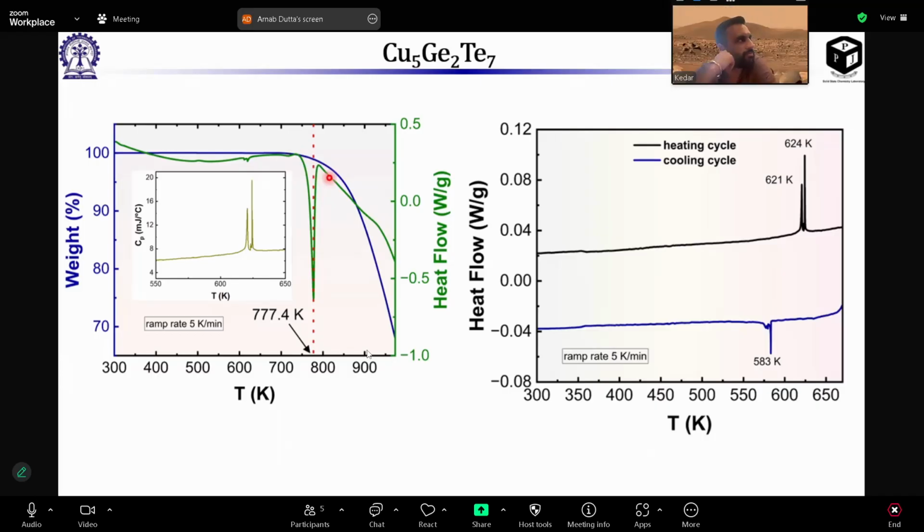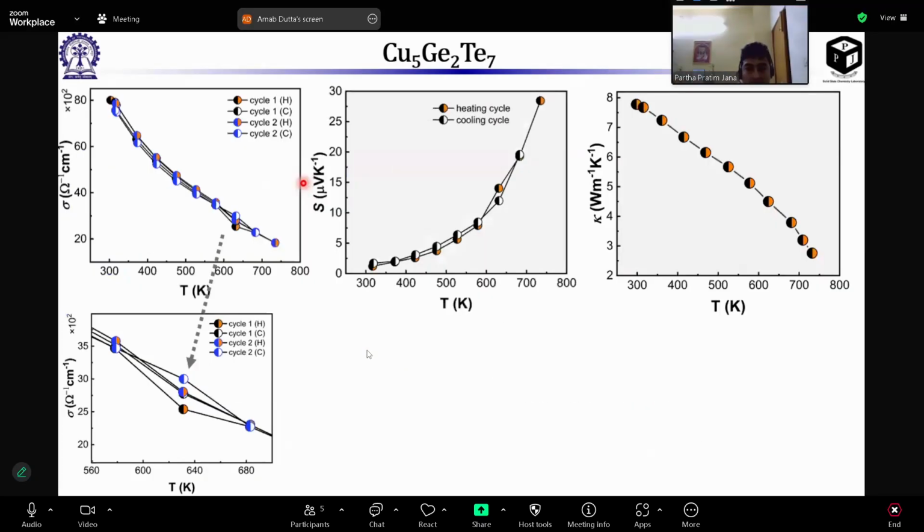That's cool. It might be good to do TEM on those for the paper. You take a sample as made, and then one that has gone through the DSC cycle, with the precipitates forming, if the majority phase is still that. We should also measure the transport properties of those, because it depends on how the precipitates form. The Seebeck coefficient, I briefly noted, was positive, right? In the next slide. Yes, so it's like P-type metallic. I don't know the band structure, maybe we need to discuss it. But it's possible that if the right kind of precipitates form, then you get de-doping and might increase the Seebeck coefficient.